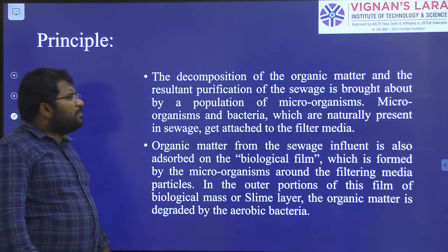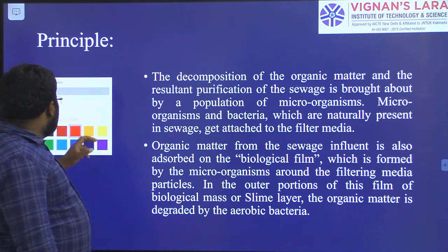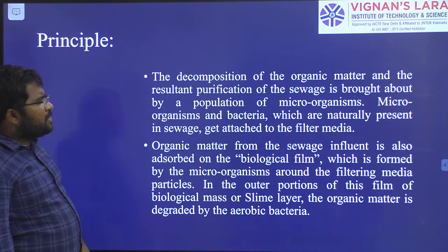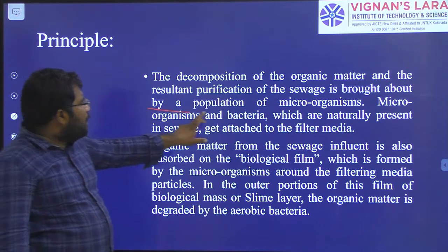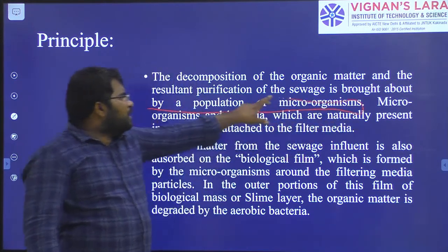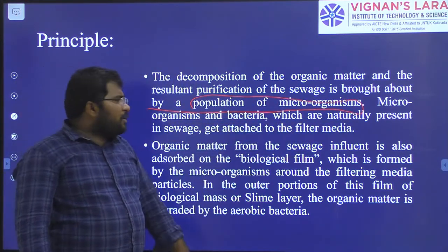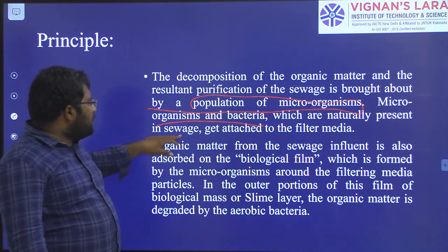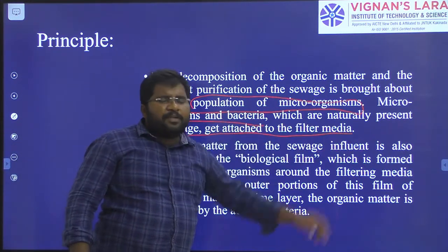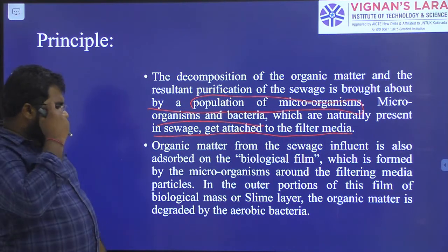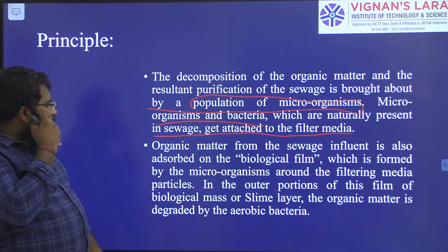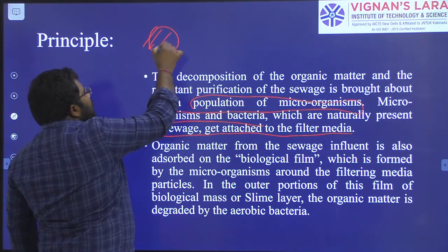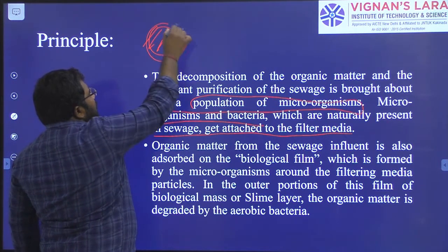The decomposition of organic matter, right? So the purification of the sewage is brought about by a population of microorganisms. Here the treatment will be done by the microorganisms. Microorganisms and bacteria which are naturally present in sewage get attached to the filter media, right? We already know that. So we have a filter media, and this filter media is going to be attached by the microorganisms.